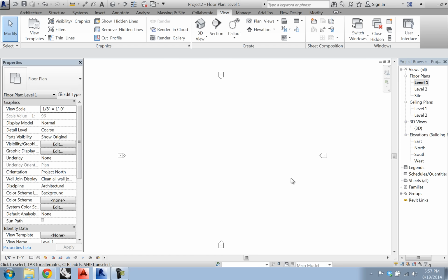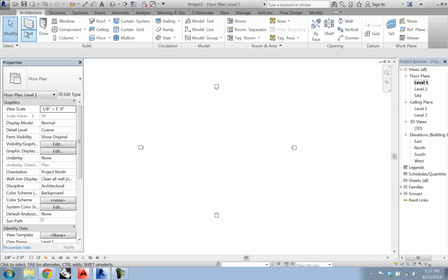So back in Level 1, you can use the middle mouse button to pan around inside of here, and you can scroll. You're going to want a 3-button mouse if you don't have one. You definitely don't want to be doing this with a trackpad all semester. You can use the middle mouse button by pushing it to pan back and forth. I'm just in 2D here, so I'm only zooming and panning. I'll show you how to get around in 3D once we create something.